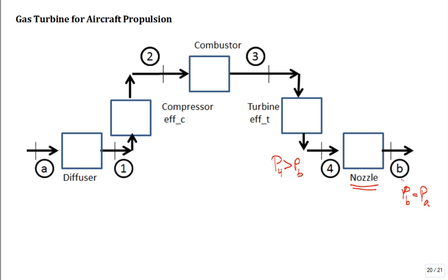This throws students as well as some other people for a loop. They think, hey, I've got this gas turbine like this. I can visualize it under the wing of an aircraft, and somehow it ingests some air in that hole and it throws some gases out in that hole or that cross section, and they think, well, this pressure right here at the exit, that pressure B, must be greater than the inlet pressure at A. But it's not.